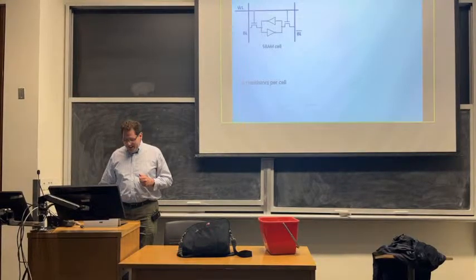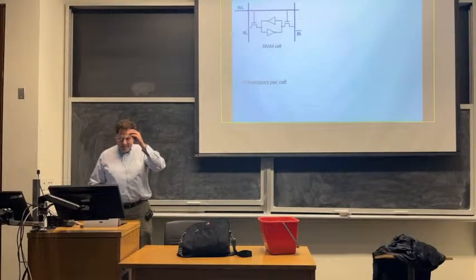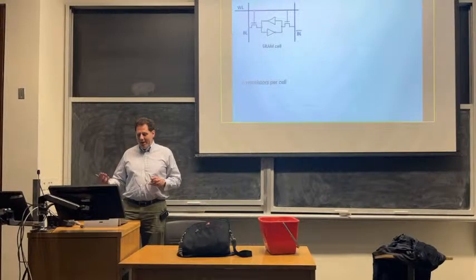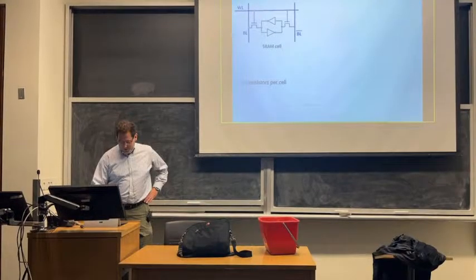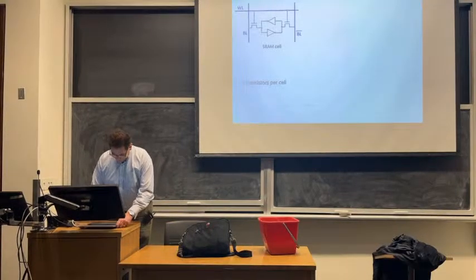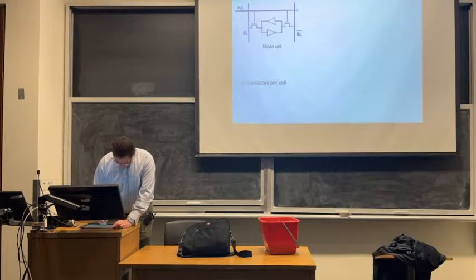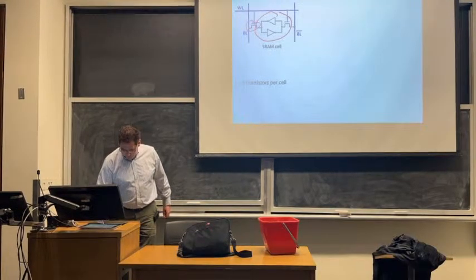Okay, so let's talk about physical RAM. I guess the most basic building block we have is the SRAM cell. And an SRAM cell looks like this. So back-to-back inverters, that forms a latch. And then we have two access transistors, here and here.